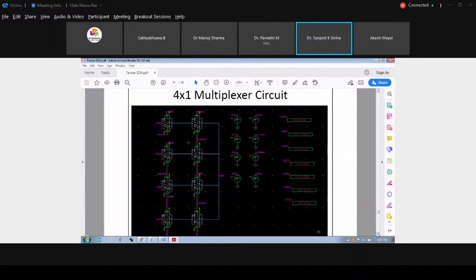Now you can see all these 7 here. A, B, C, D are your 4 inputs. S0, S1 are your select lines, and this one is your actual output. You can see clearly, based upon the select lines, we are having as output whatever is available at the input. Now when we select 0 0, what will happen? 0 0 means we are selecting the A input at the output. A is 1 here, so it is reflected at the output. So it is still 1.